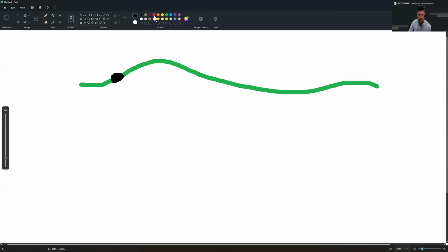The survey file, which we'll show in red, the survey builds the 3D well trajectory, so the drill hole trace downhole. So at particular depths, it's going to show a dip and azimuth. And as that dip and azimuth at a particular depth changes, that will also change the trajectory of that drill hole. Then we have points and interval files.